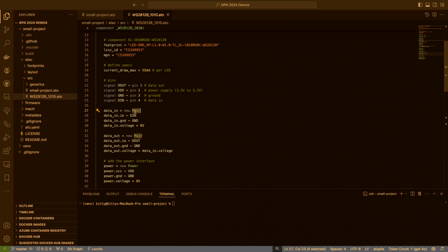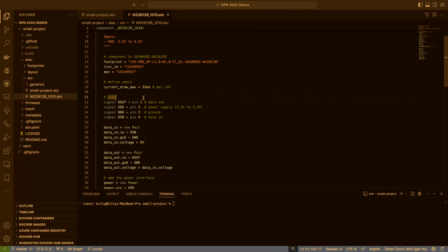And later with another component, let's say you have a USB-C port, you don't have to look up anymore what specific pin was the data plus of the microcontroller. You just say USB-C connector.USB is connected to ESP32.USB, and the rest is automatically connected correctly. And the same applies to stuff like serial and UART, which makes the whole code base a lot easier to read, and you don't have to always look up again what pins are for what purpose.